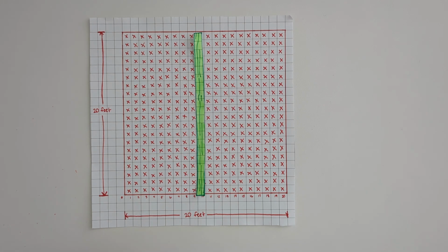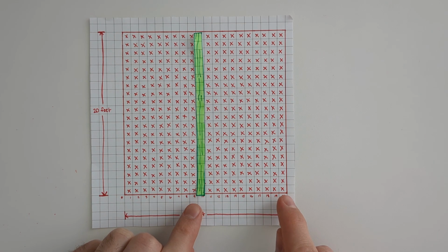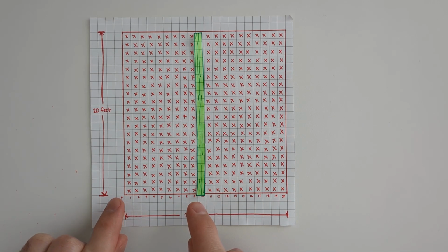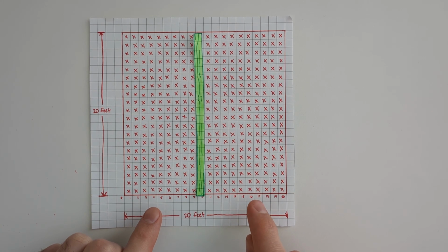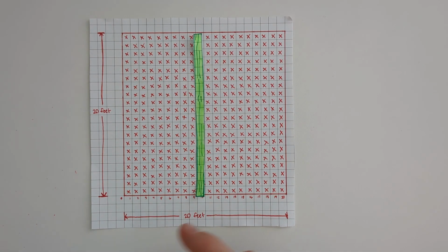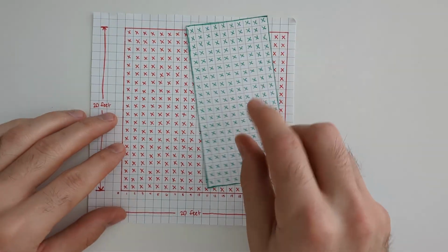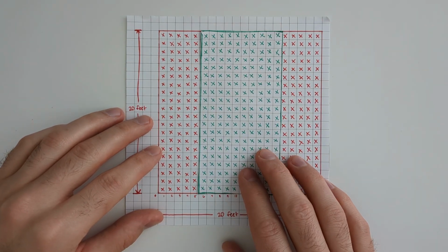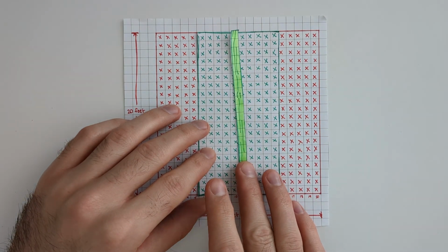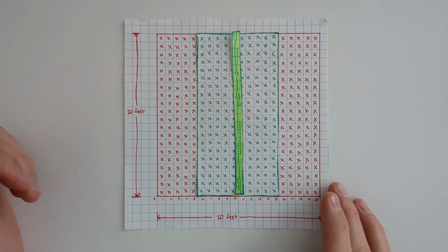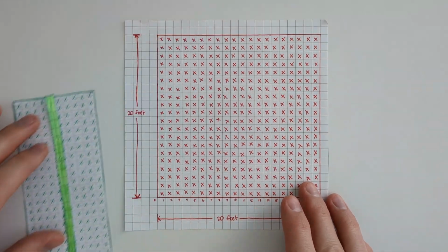So in this case, there's 10 feet to the next wall, halfway would be 5. And then on this side, there's 10 feet to the next wall, halfway would be 5. So there's 5 here, 5 here. So the tributary area will be 10 feet in width. We can see that here, our beam resting on top. Now, what happens if we move our beam? Well, let's see.